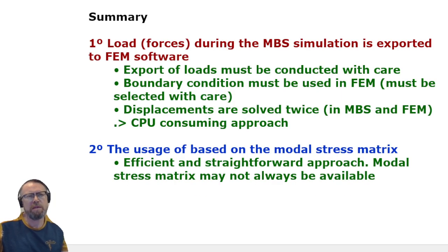So here's a summary. You take the forces and send them back to finite element software. You conduct multiple static analyses to get the deformation corresponding to each of the time steps you did in your multi-body software, and then you can get strains and stresses.